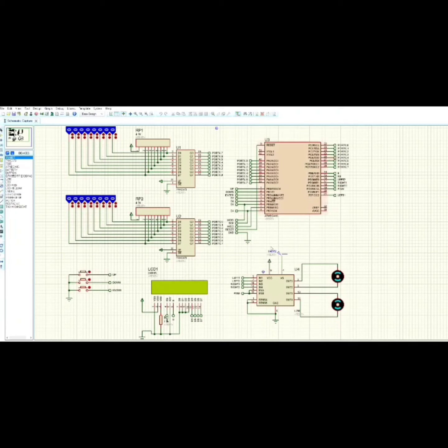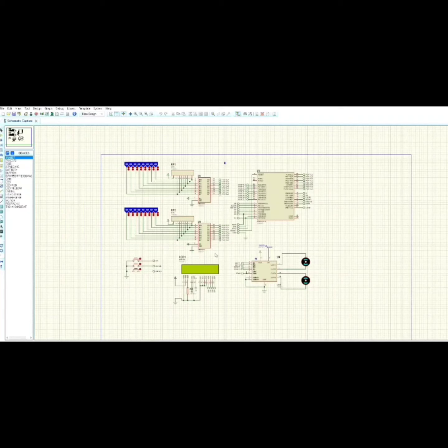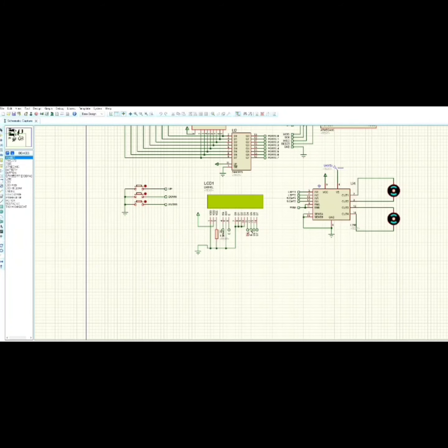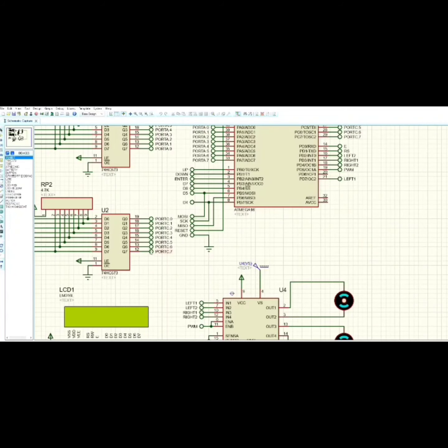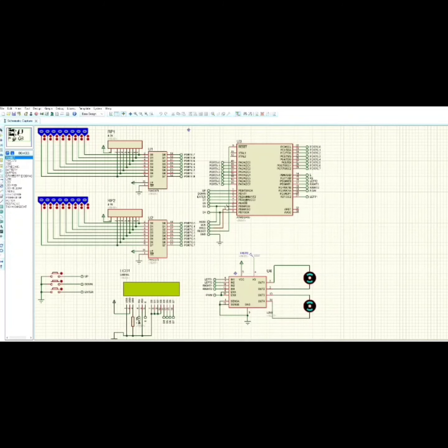And we use a 16x2 LCD monitor for displaying the information transmitted from the sensors to the microcontroller. For this you can see we have connected D4, 5, 6 and 7 to the microcontroller, which is pin number 5, 6, 7 and 8. This LCD has its own power supply at pin number 2, and we have used a resistor for precaution actually.